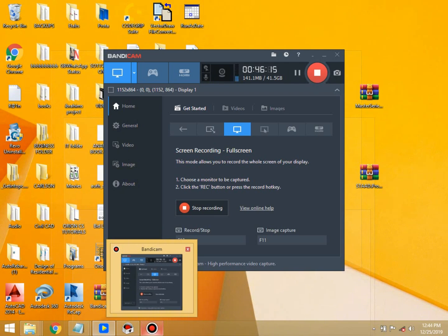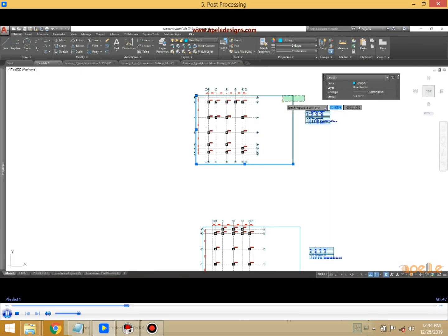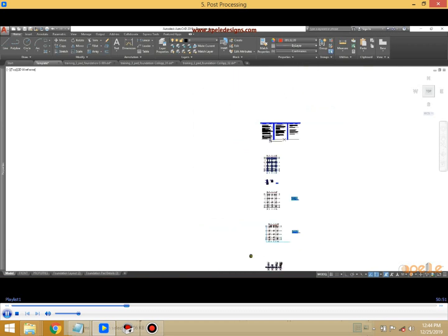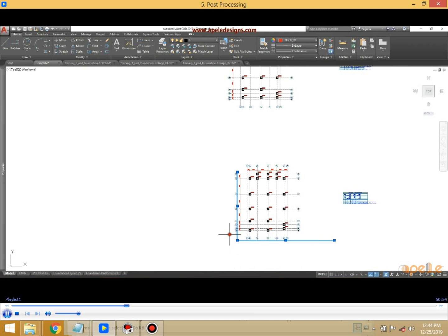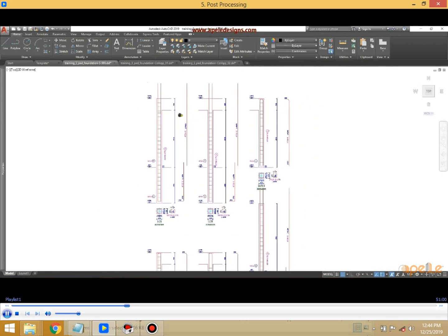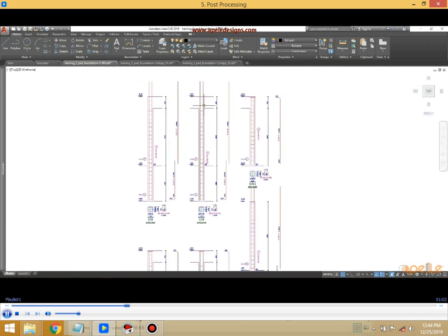And I'll delete the boundary lines. I don't need these cyan lines anymore. Let's take this out. And take it out. I'll go back to my column details. Current column details may not be acceptable in some countries, because it's really not detailed enough. So for me, I always have to manually draw my column details, and I've shared my template with you.